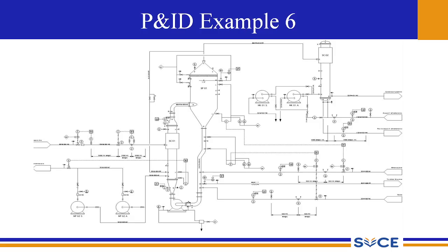So to recap how a P&ID diagram should be read, it is always read from the left to right, and the P&ID diagram should comprise a legend. So if you have a legend to interpret the information, that needs to be kept side by side so as to comprehend the relevant information. Represent all the major equipments by the corresponding P&ID symbols, and the process flows are represented by solid lines. Then the control loops are represented by dashed lines.